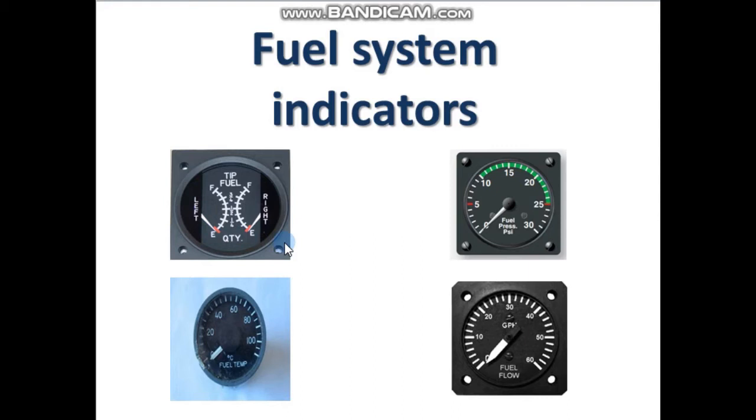All aircraft fuel systems must have some form of fuel quantity indicator. These devices vary widely depending on the complexity of the fuel system and the aircraft on which they are installed. Simple indicators requiring no electrical power were the earliest type of quantity indicators and are still in use today. The use of these indicators is only on light aircraft in which the fuel tanks are in close proximity to the cockpit. Other light aircraft and larger aircraft require electric indicators or electronic capacitance types. And this is what we are going to talk about today.